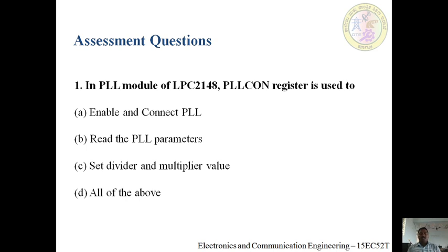And the PLL stat register is a read back register, a read only register. You need to get the status of the M and P values, that is the multiplier and divider values, and also the connect and enable bits, and also the lock status, whether it is locked to a particular frequency or maybe variable. Okay, so these are all the things we have studied. Now let us look into some of the questions.